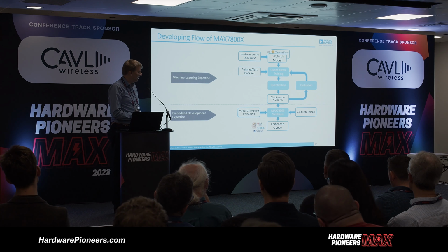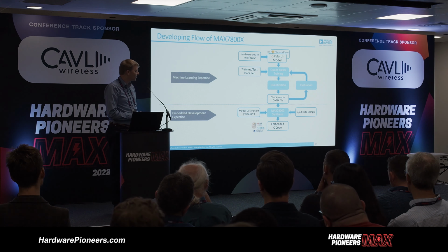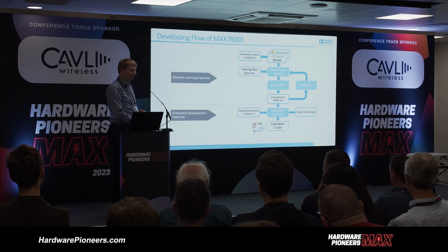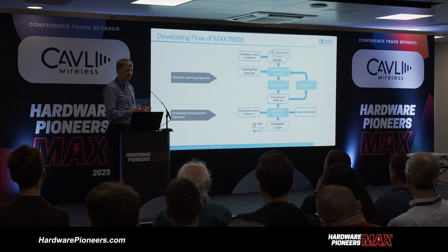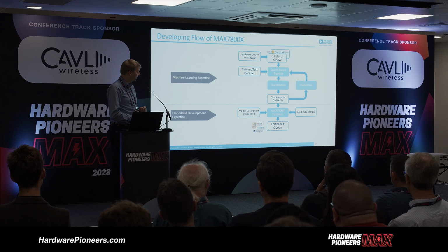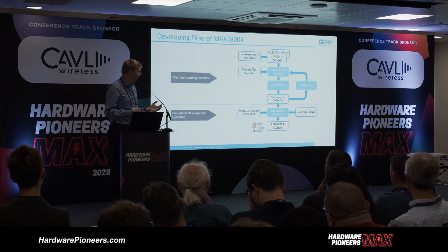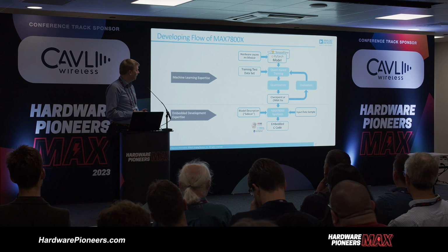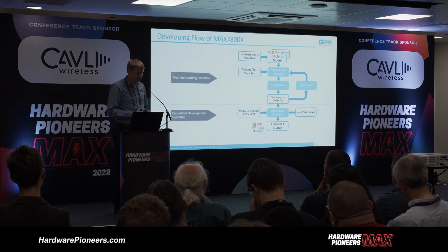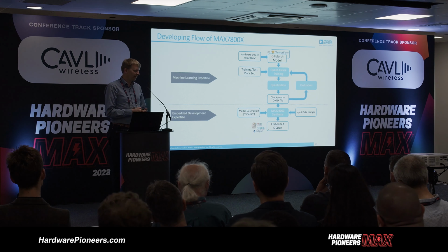And the last layer is the synthesis layer, where the result will be an embedded C code. So you actually get header and C files out of here, which hold the network structure, all the weights and the kernel memories, and you take that and include it in your standard MCU environment like Eclipse, Keil, IAR, or whatever you want to use. And that's the development flow.